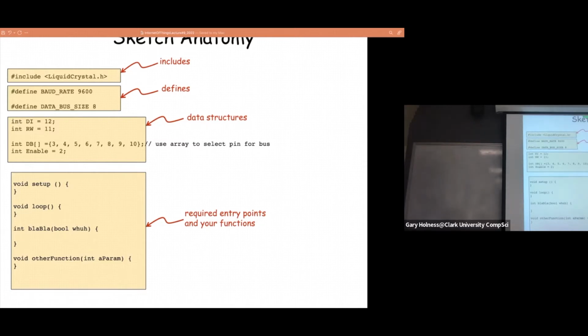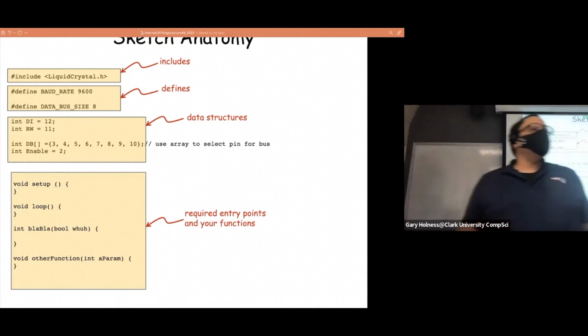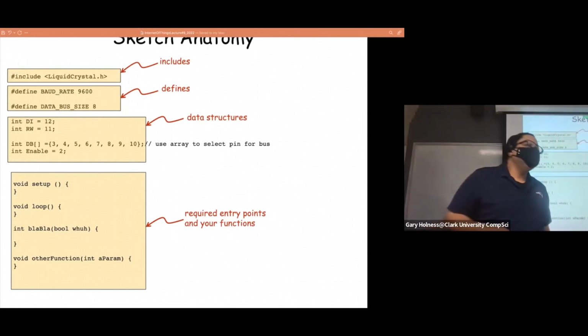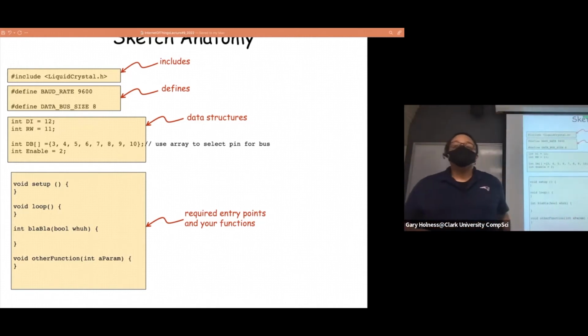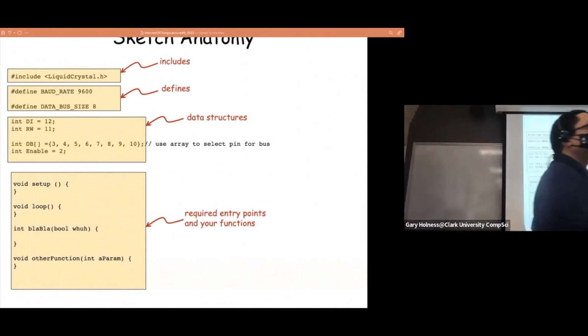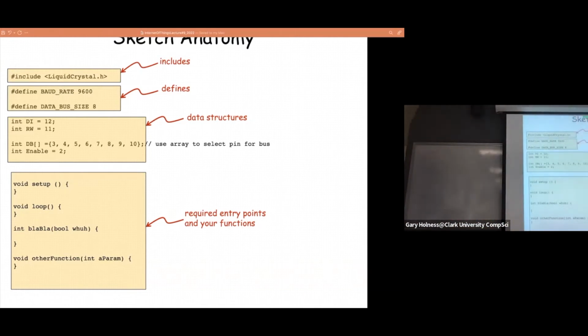And so one question that we had is, can we use variables? Yes, you can for things that could be defined, but the difference is when you use variables, there's overhead for your runtime image. Variables take up space, whereas number sign defines do not, because the preprocessor does a find and replace with the defined specifications. Any questions about this? No questions?